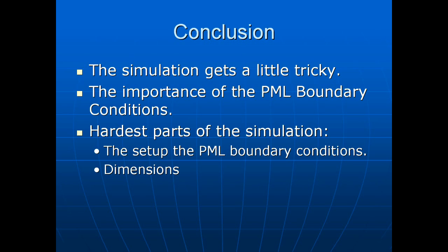Therefore, the PML uses an absorbing region rather than a simple boundary condition like the ABC. So to me, that's pretty much the main difference between them: the PML provides lower reflections by an order of magnitude, and it is more of an absorbing region rather than just a simple boundary condition like the ABC. Those are the important things distinguishing between the PML and the ABCs.